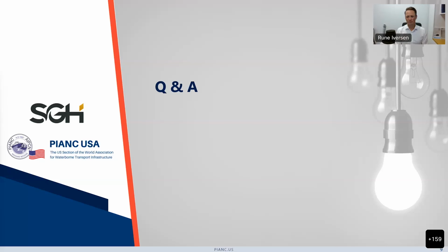Okay, that's great. And our next one, has data been collected on past failures for fenders designed in accordance with the past guidelines? Not that I know about. The problem is, if you have a fender that's failing, and you want real data on what actually happened, you need to have a berthing velocity system in place, which tends to control berthing velocities better. So I don't think there's a huge number of data points available there.